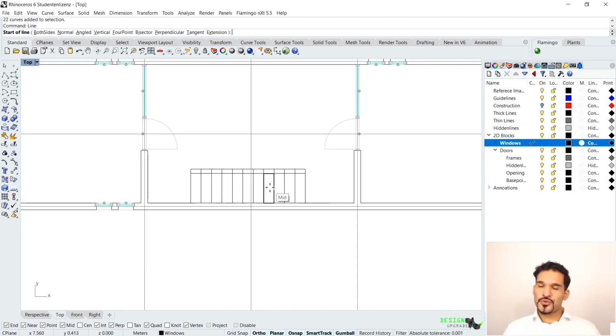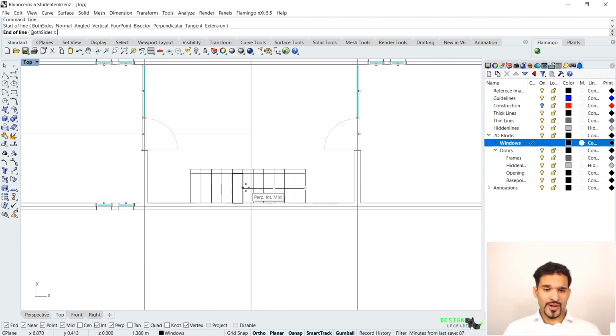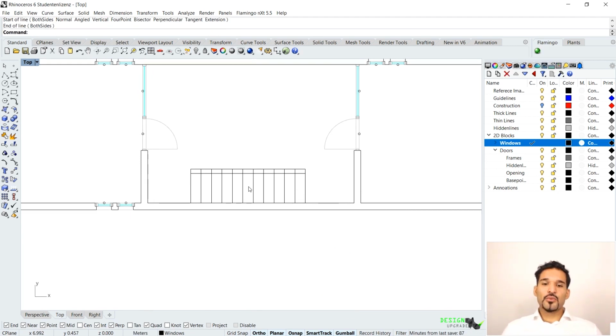Now the first thing that we want to do is add an arrow, right? And as a rule of thumb, I mean, it really depends, but because this is a section of your first floor, you will cut through the stairs, right? So you somehow have to display that visually, always in drawings, that you want to say, hey, these stairs are cut. So everything you see to the point you can actually see, then everything else is actually hidden because you can't see it anymore, because you're cutting, let's say, on a level of 1.5.